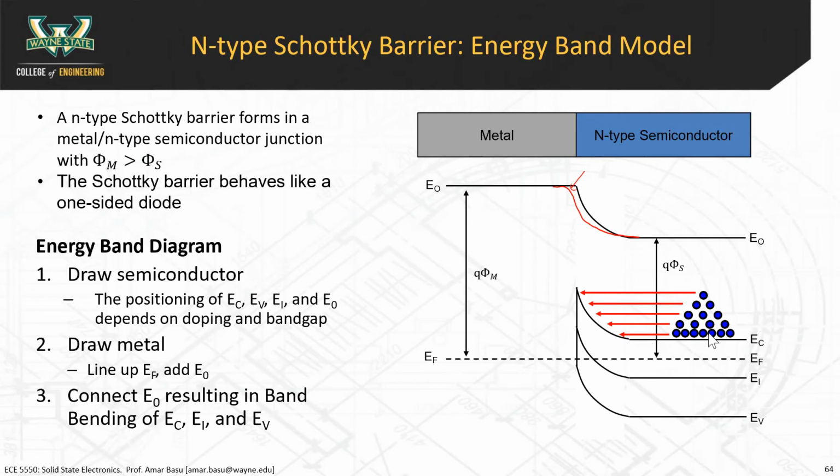What does that equilibrium mean? Well, because you have this slope in the band diagram, that means you have an electric field. What does the electric field tell you about built-in potential? There is a built-in potential, just like there is with the diode. Correct.